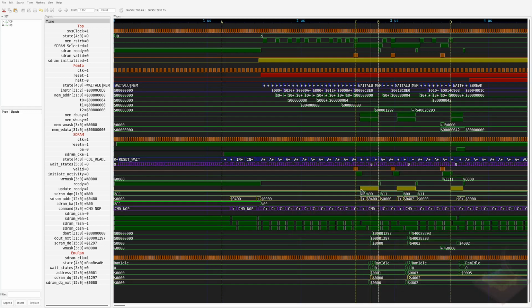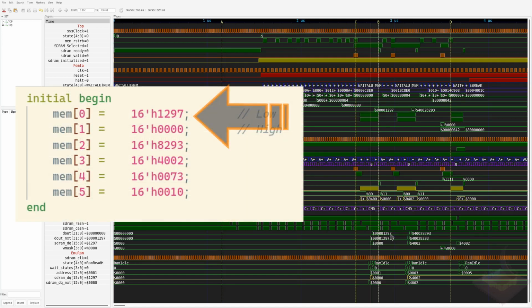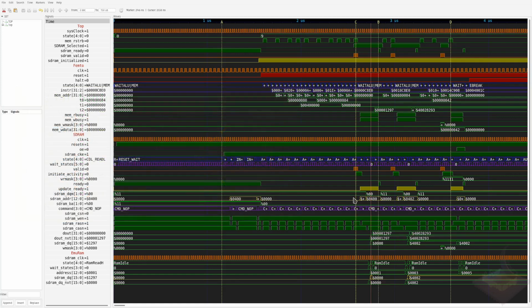And when it does a read, it's going to activate the ready flag so that it's doing its thing. That looks normal. The data that's coming out looks about right. I'll zoom in here to make sure that's correct data, but it does look like it is. If we go back to the EMU RAM, that's the data that's sitting in the first 2 half words and then the next 2 half words. So at a high level, this thing looks like it's doing what it's supposed to.